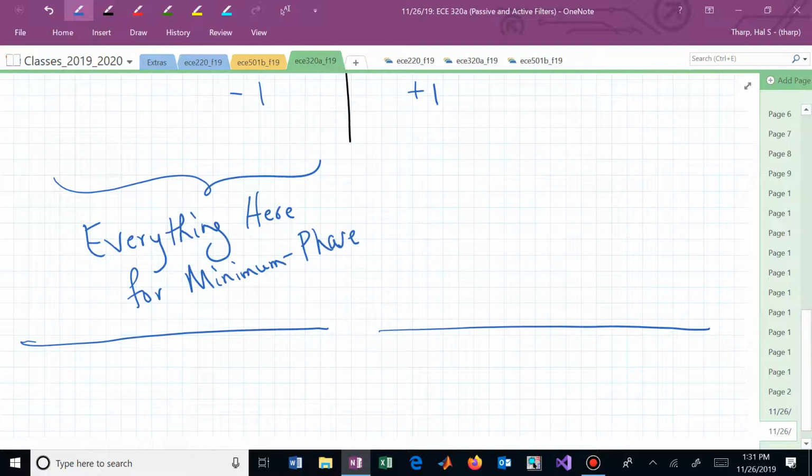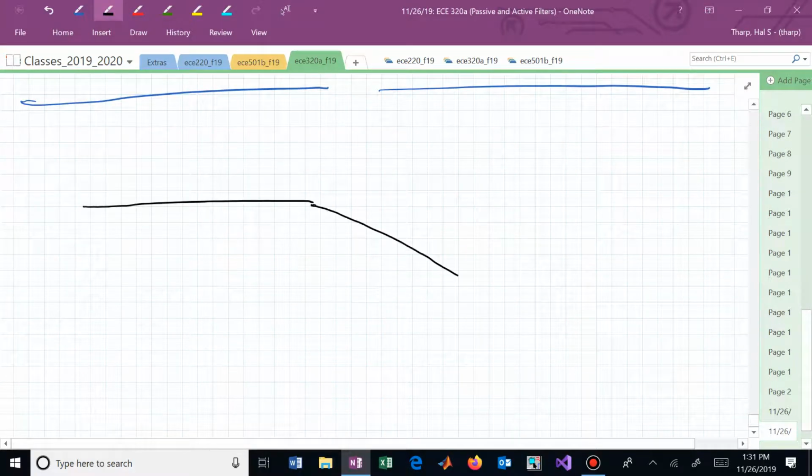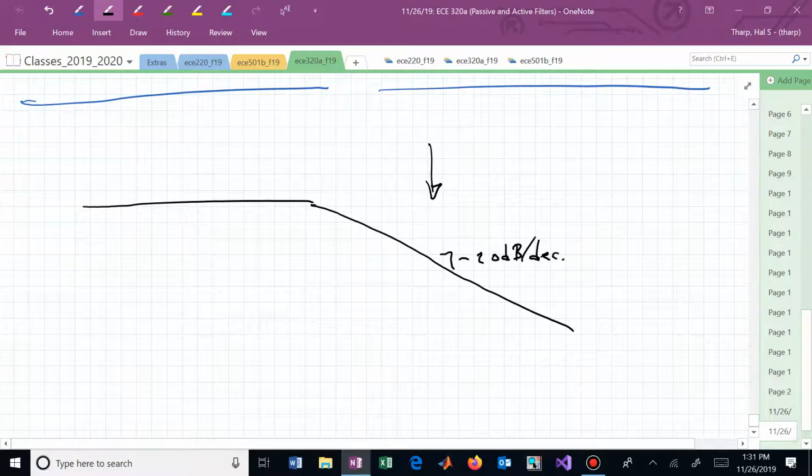I've kind of given you the answer. You can use a second-order filter or a higher-order filter. Do you see now that when we're designing filters, a first-order one may not cut it if this is minus 20 dB per decade, if we needed to be attenuated by some amount at that frequency.